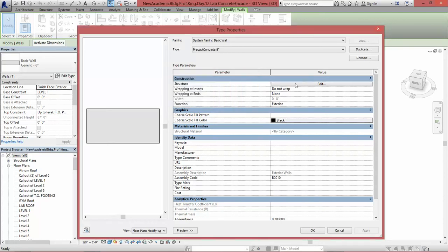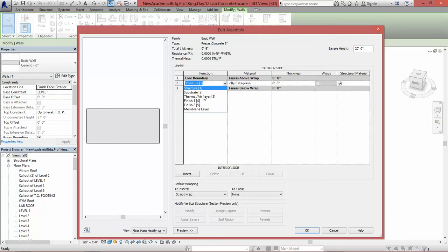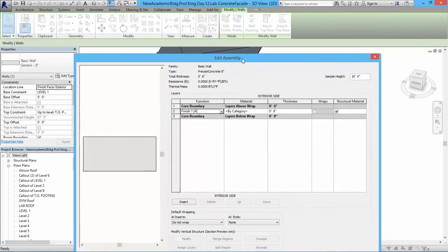Say okay. I'm going to edit, and it is structural, not for the building, but structural as in it holds itself, similar to a curtain wall system. Depending on how this precast system goes, if it's between slabs, or if it flies out in regards to the slab, it could be structural or not structural. It could even be a finished material. So I'm going to say finished, because in our case we have the columns that are actually the structural elements.